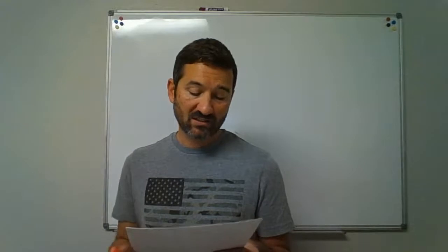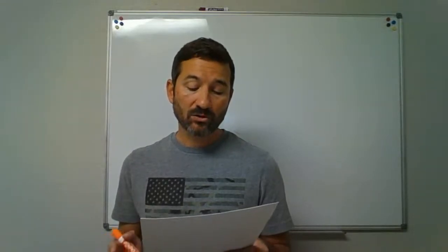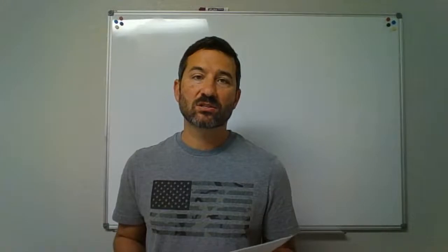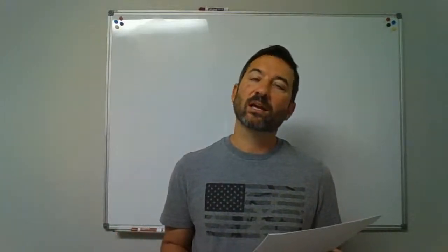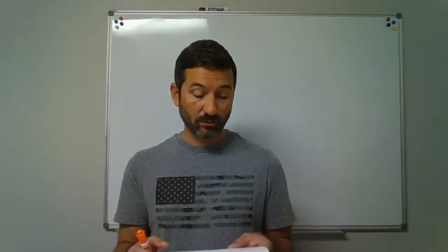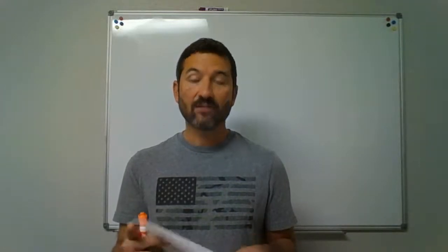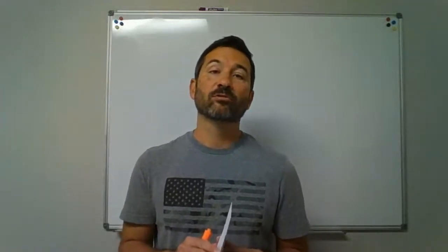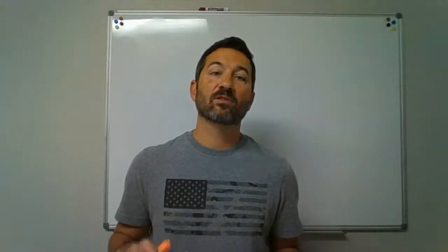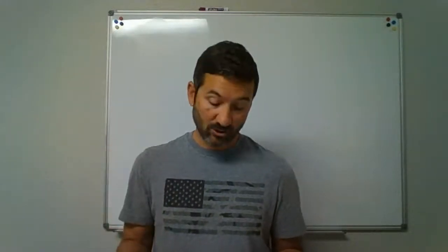Question 5: the vent stack can connect anywhere in the drainage system that you can find room for it. The vent stack can connect anywhere in the drainage system wherever you can find room for it. Say, "I've got a little spot here, I'm going to just put it in. It'll be fine anywhere I want to." Question 6: when the roof is accessible, the vent must extend at least 7 feet above the roof. When the roof is accessible, so if you have a little sun deck up there or whatever, the vent must extend at least 7 feet above the roof. Is that true or false?